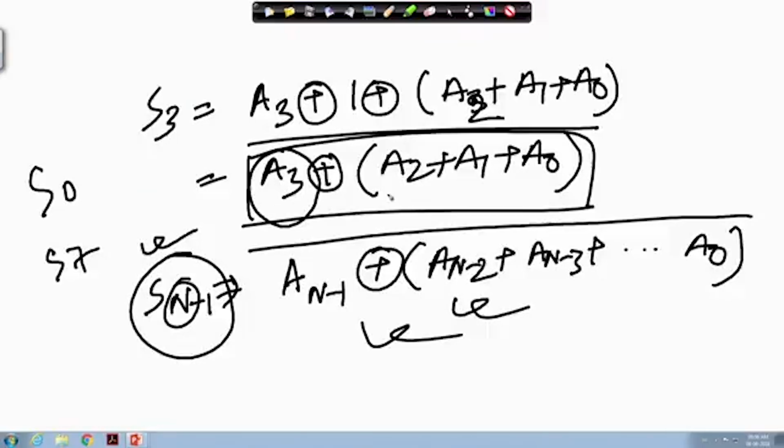Okay. So, now if I want to map this 4 bit expression we have got to the architecture, you can write this expression using any HDL language. Whenever you do the synthesis, at that time it will be converted into the corresponding gate level netlist. That means it will be implemented using the corresponding gates.